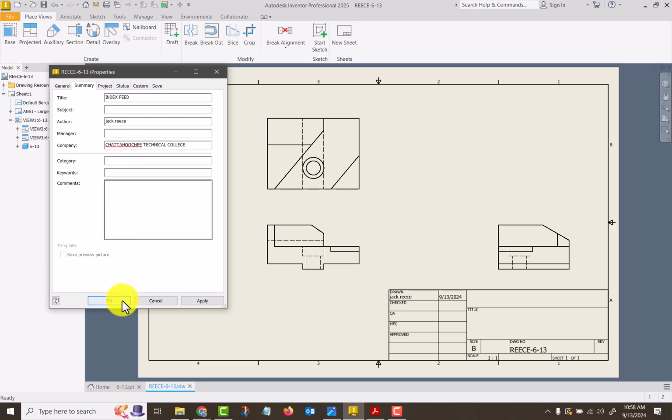Okay, now I recommend that you use all caps because that's the standard way of doing things from back in the day. All right. And the reason for that is that we lettered in all capital letters because it was easier to read than lowercase letters. Because lowercase letters, you could mistake Q's and G's for each other. Some people draw their A's differently than others and things like that. So when we did lettering, we did it all in upper caps. And I recommend you continue that.